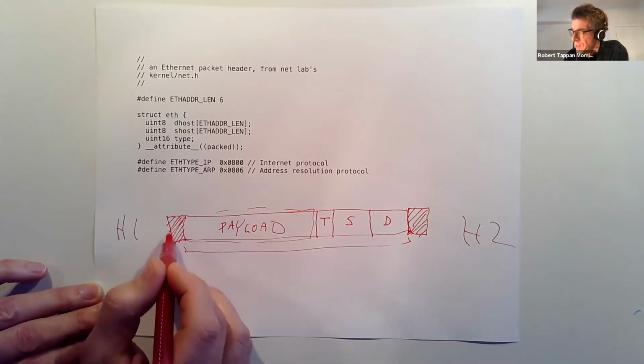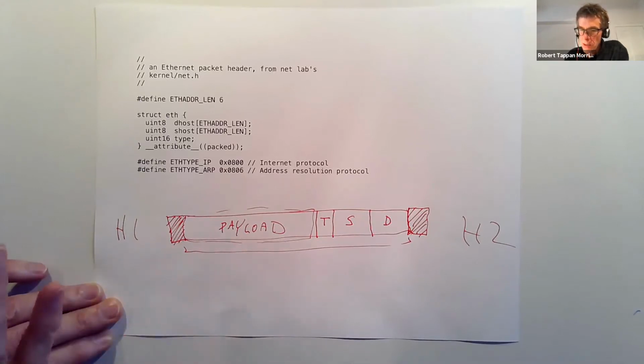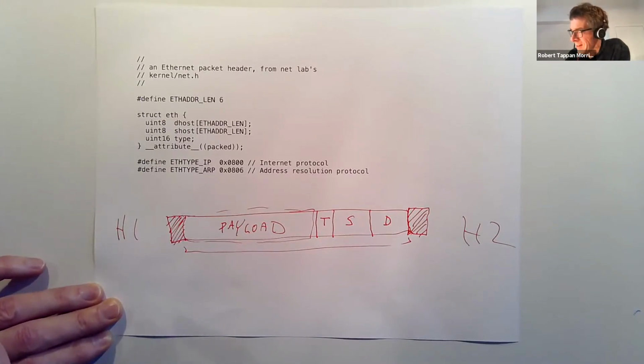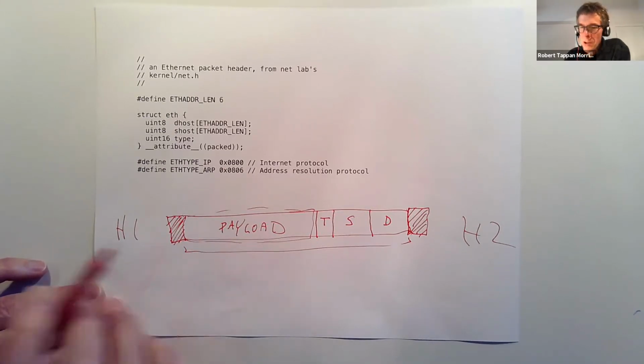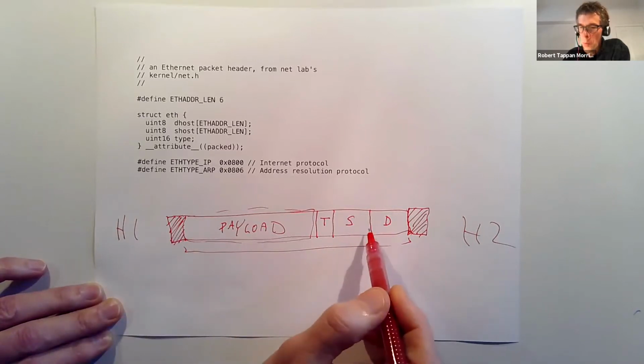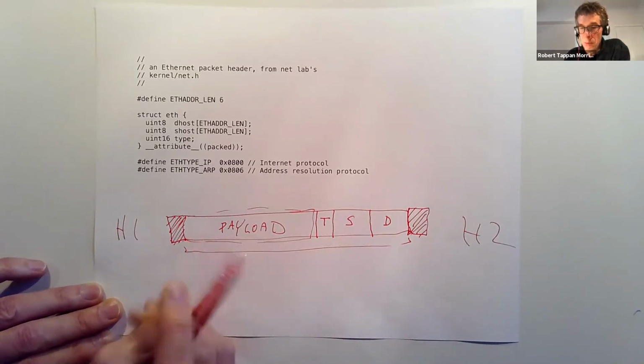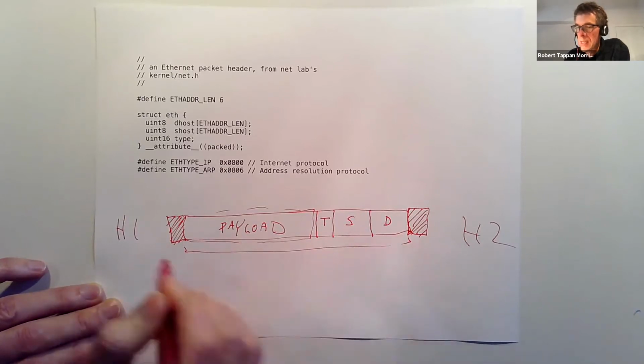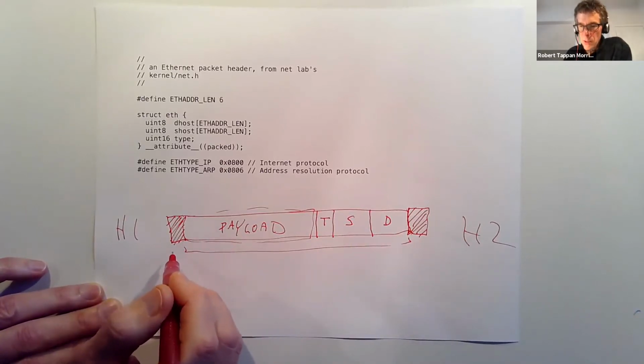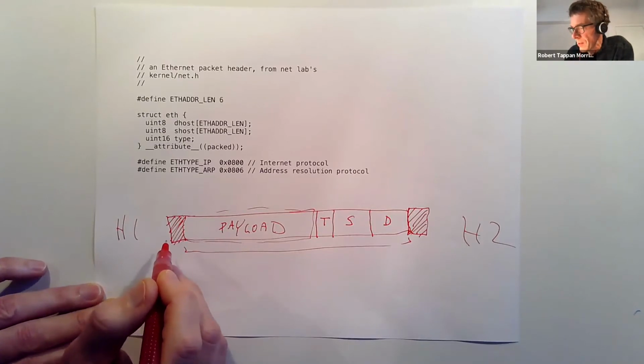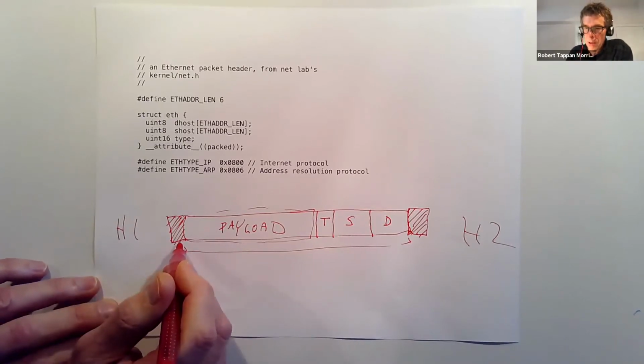One scheme is, instead of just sending 0 or 1 bits over the wire, you could send sequences of 2 signals. So there are 4 different symbols possible with sequences of 2 different electrical voltage levels or something, and have 2 of the 4 possible symbols indicate 0 or 1 bits in the body of the packet, and have the remaining 2 indicate beginning and end. That was in fact a scheme that was used years ago, a scheme much like that was used years ago in Ethernet. I don't actually know how it works now.